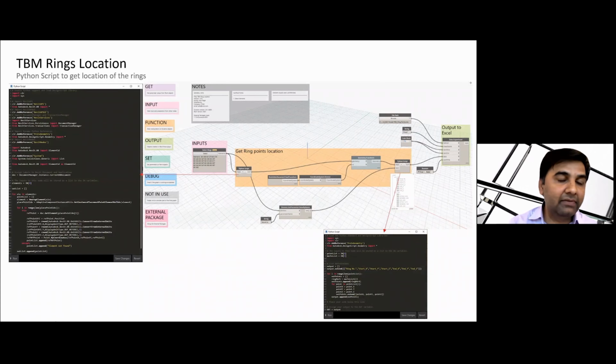We already have a method in the Revit API that selects that element and gets the instance placement point element reference ID. It extracts those points as other elements, and after iterating through all of them, we get their positions and then convert those positions to whichever units you want.